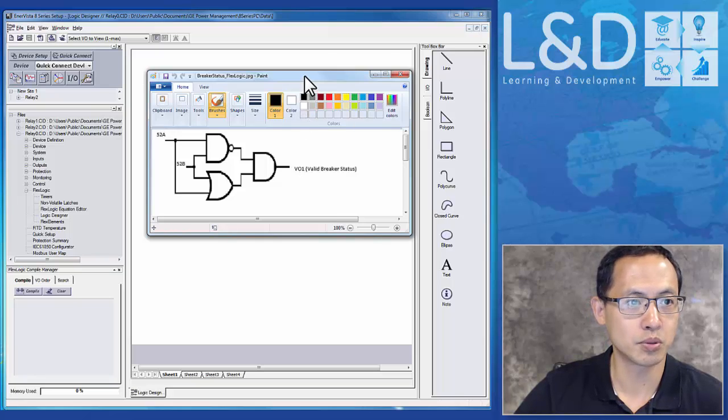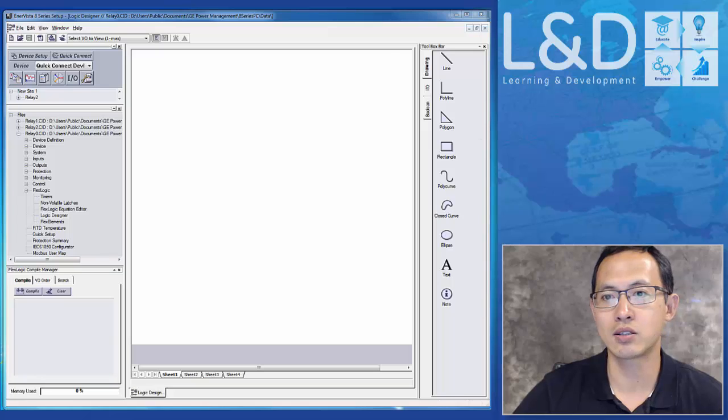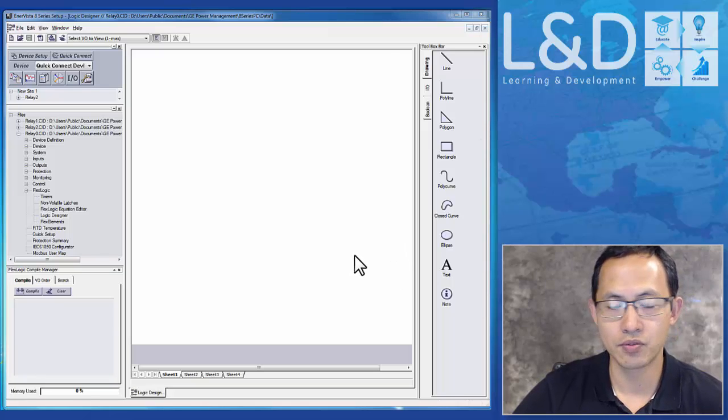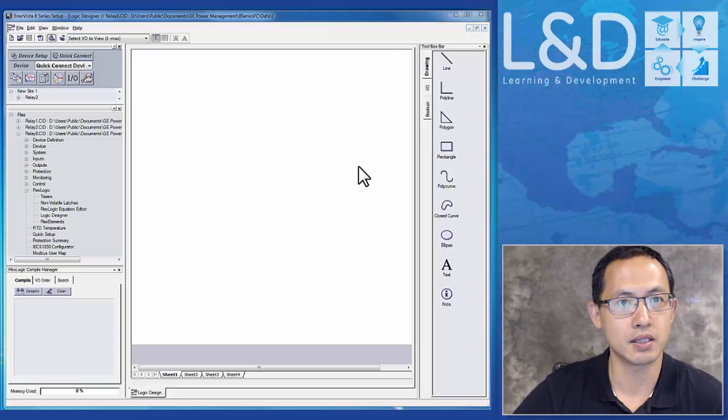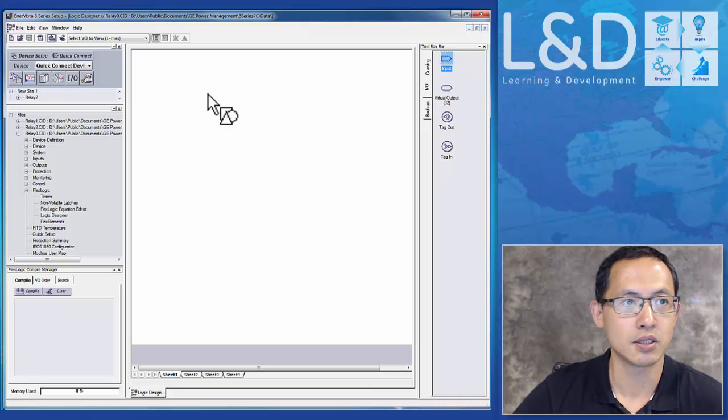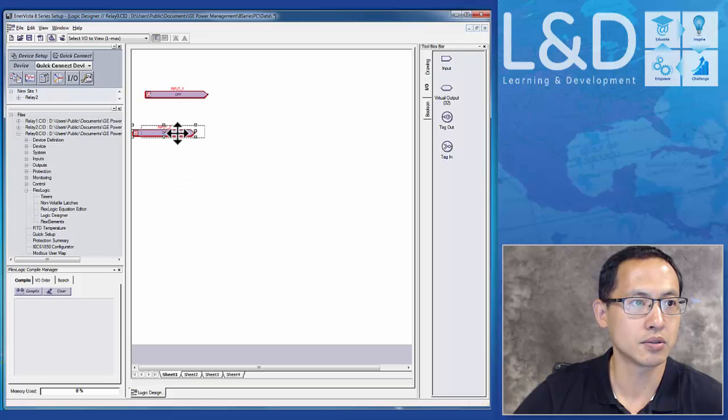We're going to program this in the Flex Logic editor. We're going to use contact input 1 from the relay as the 52A and contact input 2 as the 52B. First we need to choose the IOs. We need 2 inputs, contact 1 and 2.